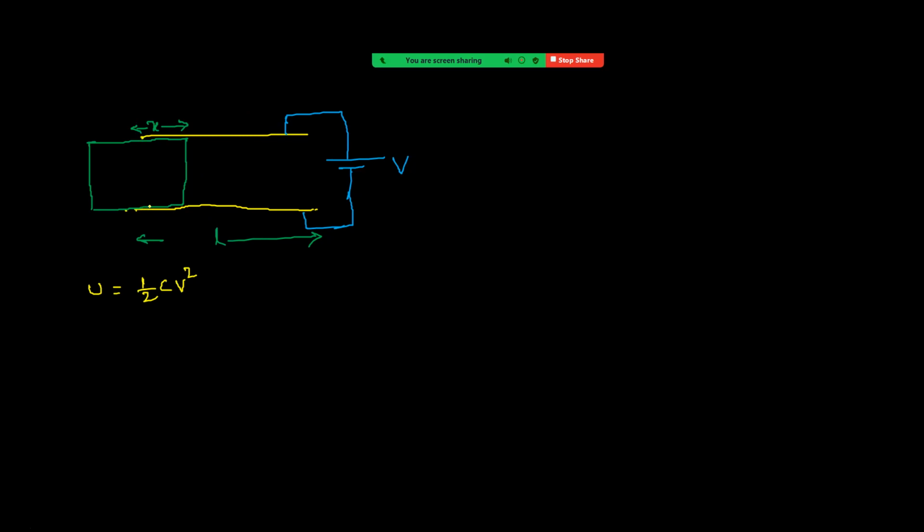This is just like one capacitor, a capacitor which is completely filled with dielectric. And the remaining is now an air capacitor. That means this is now air medium. And you can see across these two plates, we have the same potential difference. That means capacitance is written as C equal to. So coming to the area, what is now the area?